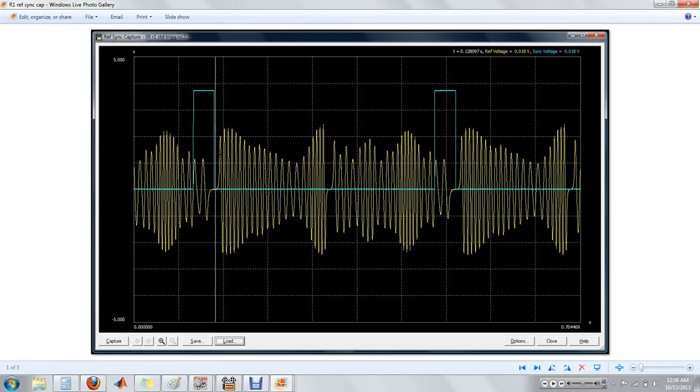There is an importance in what you have it set at, because sometimes if your edge is close to, say, these missing teeth we see here, what could happen is that, at higher RPMs or varying engine loads, you may have some slop in your chains and your valve train, which will shift the sensor reading just a little bit.